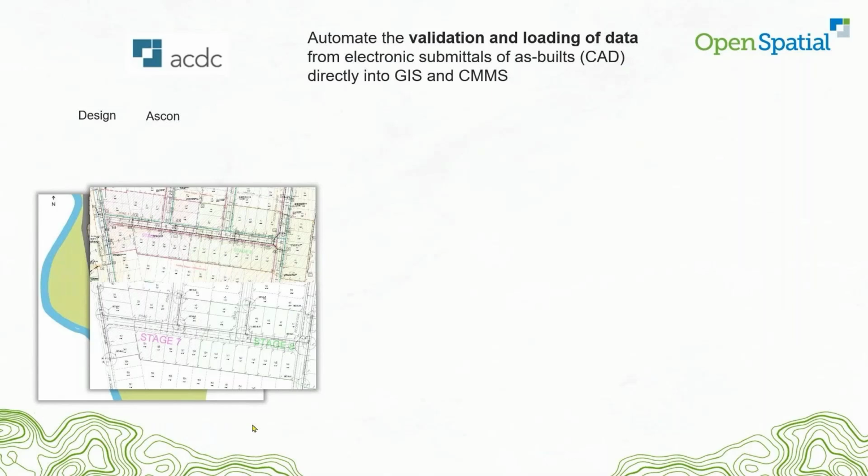And then furthermore, when you check that drawing, is the topology correct? Do you have point features that are isolated when they're supposed to be connected to a network? Do you have a network that is missing all sorts of point features? What if you have a long CAD line and it has a bunch of things on it like valve, valve, valve, but in the GIS you want that as a segmented network.